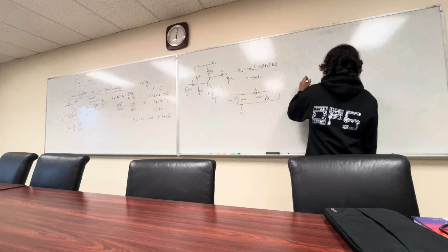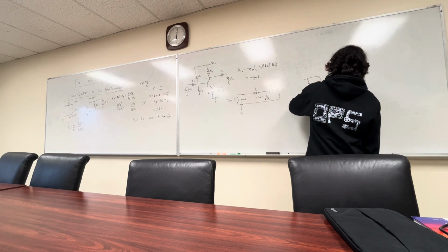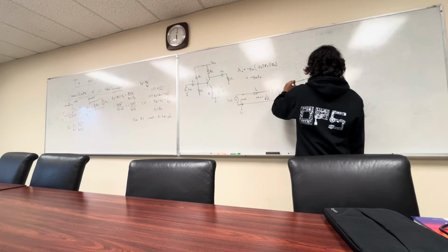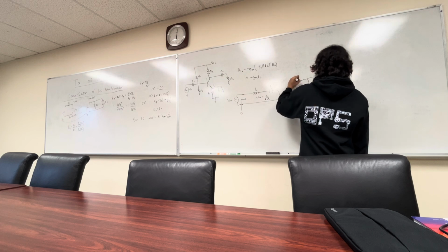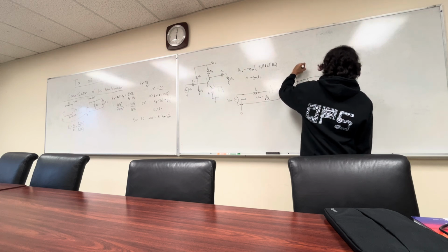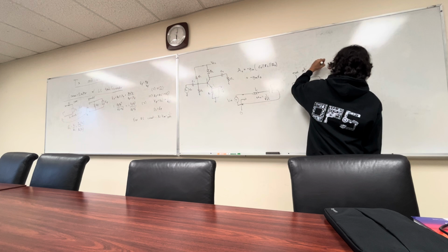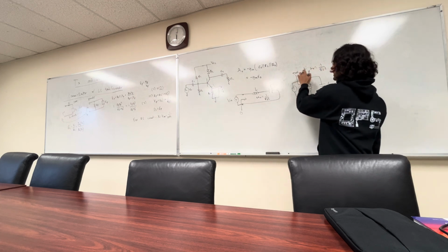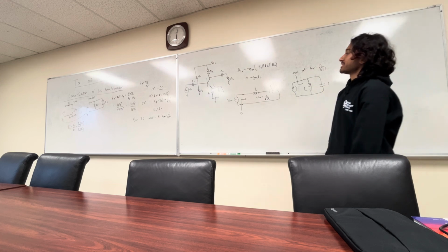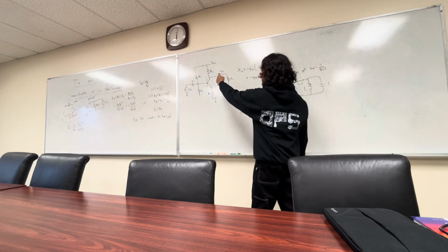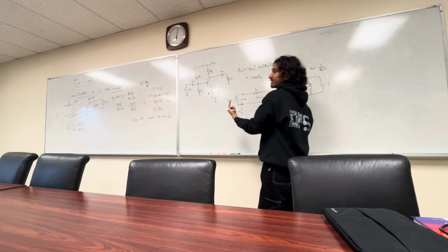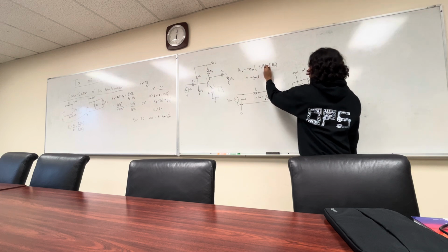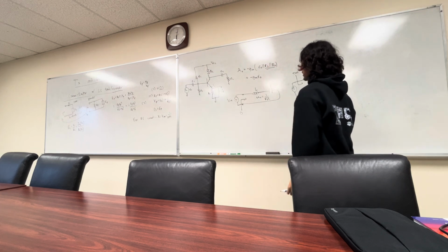And we make these parallel. That's not an inductor. Same scenario, same resonance frequency. It looks like an open circuit, right? So, infinity. Okay, so we get an infinite impedance. So ideally, we want to insert some network up here such that when looking into it, we see infinite impedance. That way, this term goes to infinity, and all we're left with is R0.